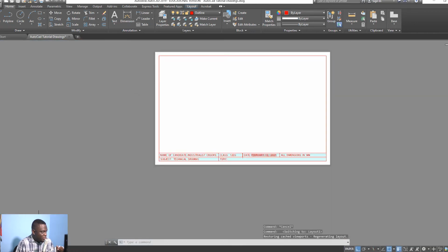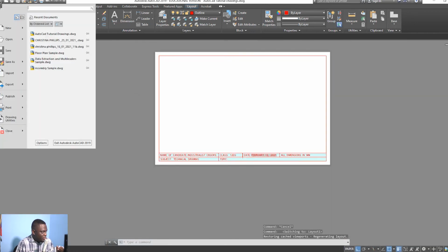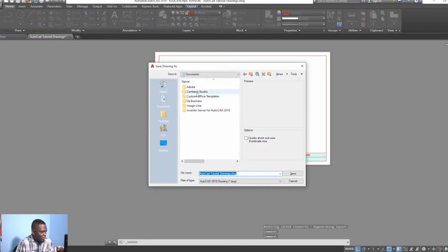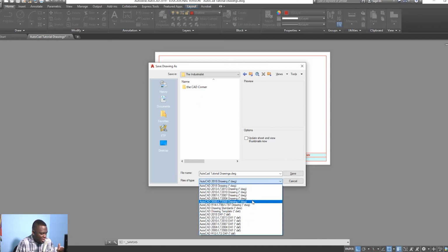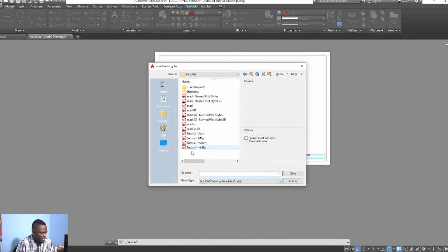So I'm going to go to File here, and I'm going to go to Save As, and then I'm going to create a DWT file. I'm going to go to documents.